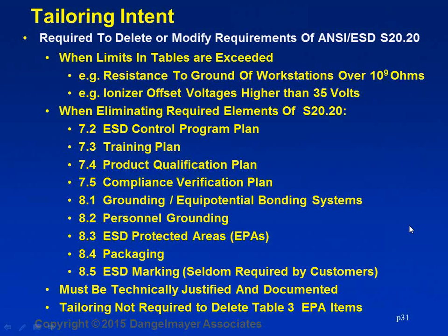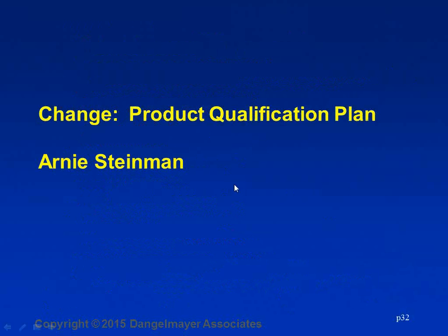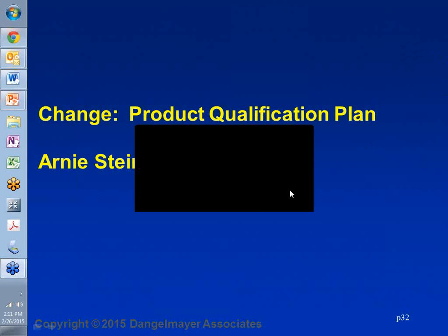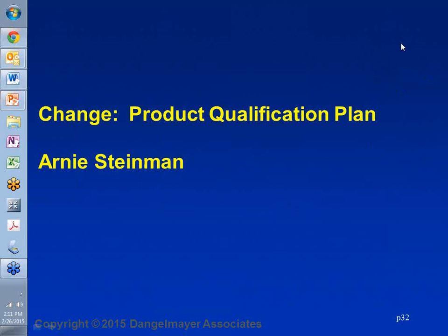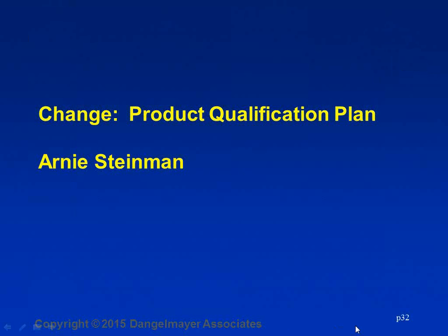Rubber floors are even more durable, but we often recommend letting the data help you guide how often you need to do testing. So if you start out with a very tight test schedule, as Ted mentioned, and you don't find any deterioration, then you could lengthen the amount of time between tests. But always test in the working conditions. So don't clean the floor first and then test, because now you've changed the conditions that it's actually functioning under. So test it in an as-is condition in the high traffic area, and that should help you decide how frequently you need to test to make sure it stays within your guidelines. Thanks for the good questions, everybody.